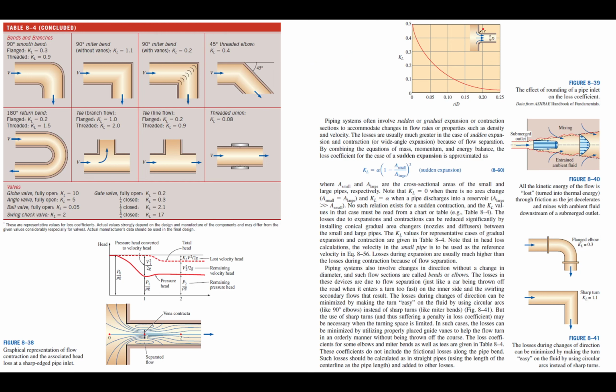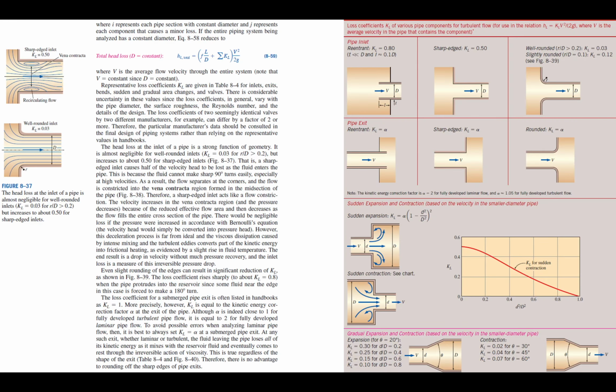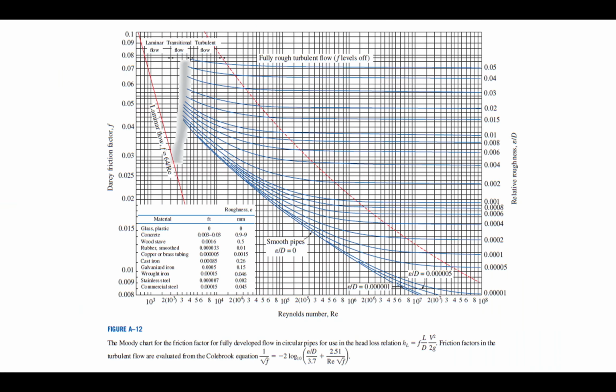You do not need to remember all the K values, because generally the K value is given in any question, though the derivation is sometimes important. Also always remember the Moody's diagram, because people forget how to calculate HF. After you leave the fluid mechanics course, you may forget how to calculate the friction factor in turbulent flow.